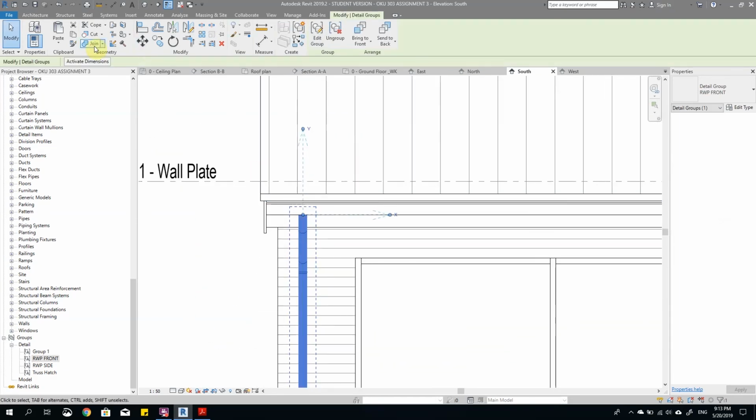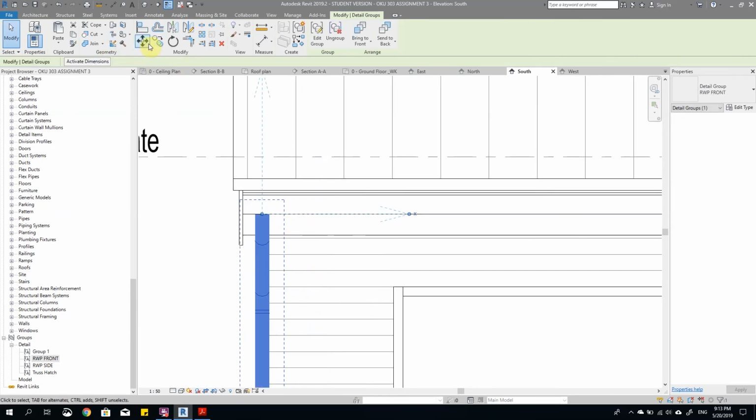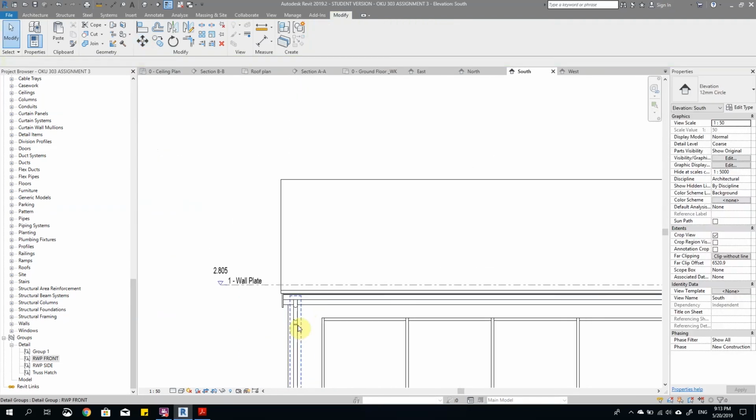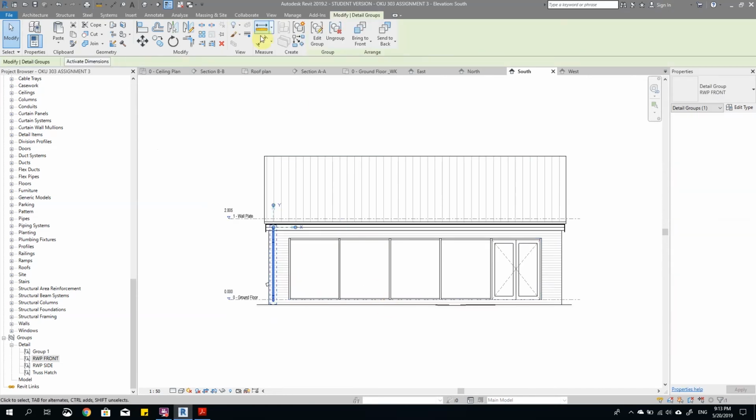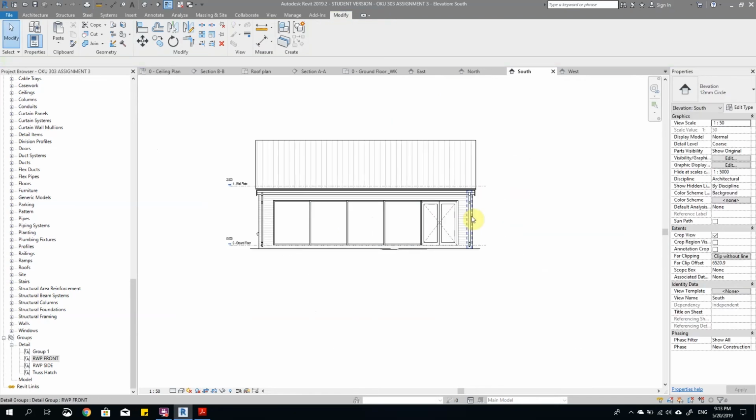Okay, this I'm going to move. So let's move it from the end of the wall. Let's move this 150 away from the edge of the wall. It will work. Select this guy, mirror, find the, so snap M for middle of the roof, SM, and you're going to mirror it around there.